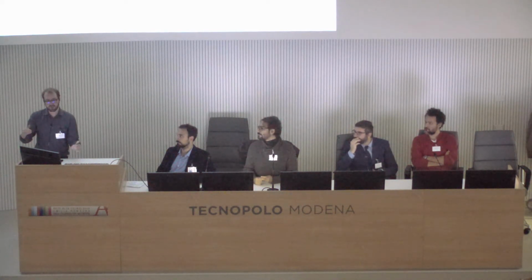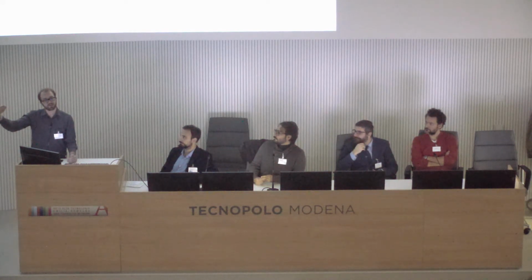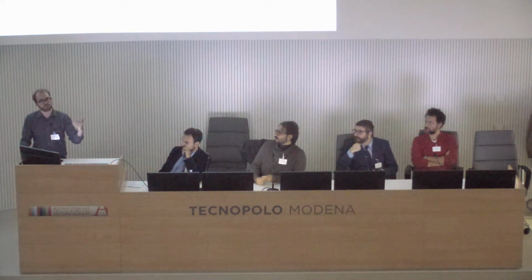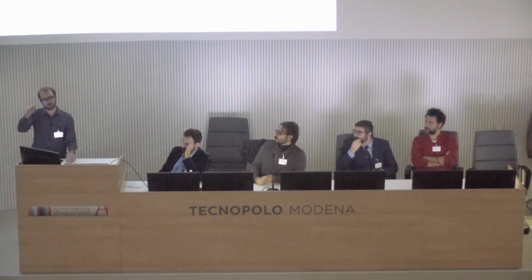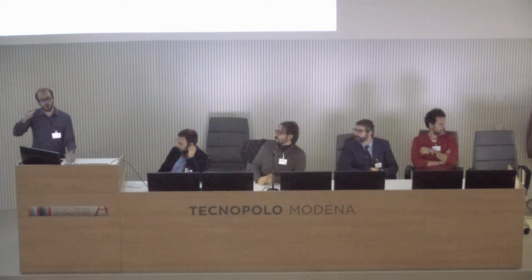We computed the stress intensity factors for a significant number of different crack sizes, and we showed that the bigger the crack is, the smaller they are, because they're getting closer to the compression state. Maybe I have an image afterwards. I don't know if I included it in this one.